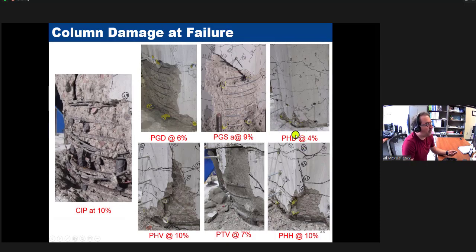And what we found later was this coupler was supposed to be seismic. That's what the manufacturer told us and showed us the result, and they were right. But when they shipped this to us, for unknown reason, following all of the procedure, this coupler did not perform as a seismic coupler. Bar pulled out from it.